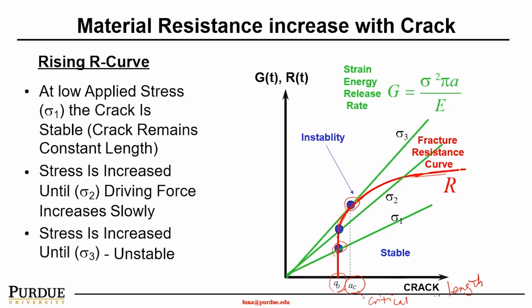Therefore, it's very important for us to use non-destructive testing methods such as X-ray diffraction, X-ray tomography, ultrasonic testing or ground penetrating radar to identify the defect size and to understand if it's smaller than the critical crack length under the specific loading condition.